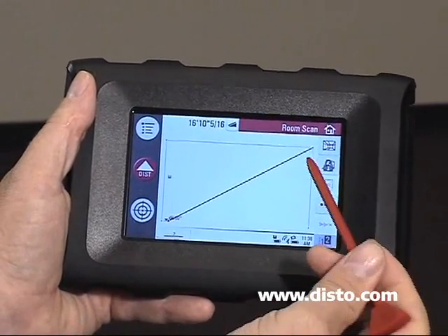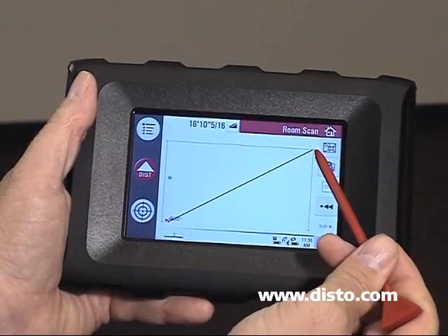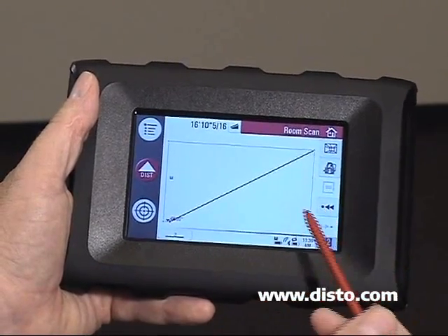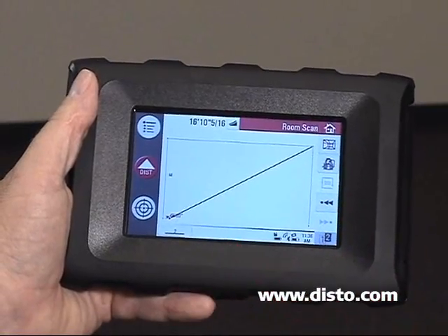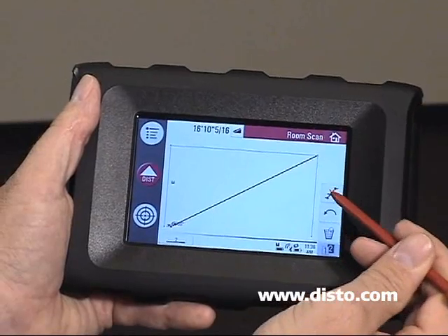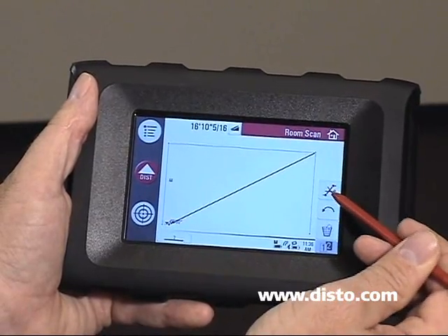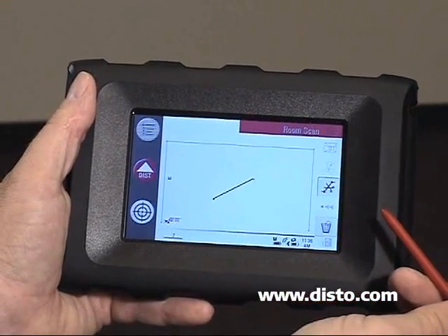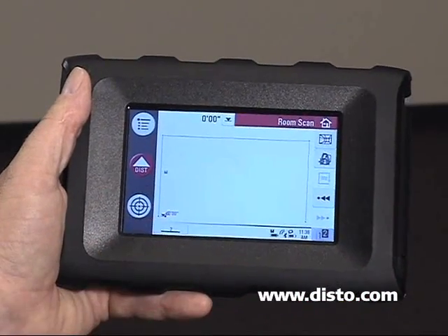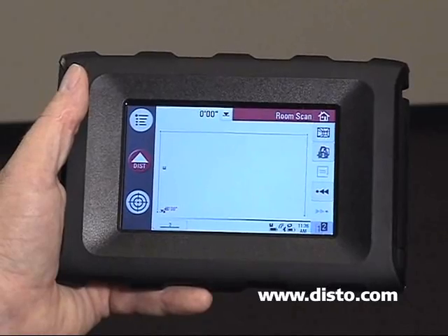Now you'll see I've got a diagonal line from that last point up there, which is point 3, to our new point down here, which is point 5. We don't want a new line segment from the last point to the new point. So we're going to drop over to screen 2, and there's a scissors with a cut symbol. We're going to hit that symbol. It's going to take that line segment out. So now down in the bottom left corner, I've got point 5 all by itself.